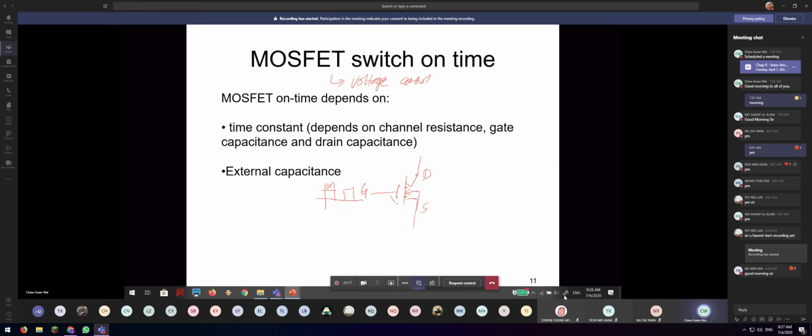Of course, you need to have a sufficient VGS to make it on. Normally the value is about 4 volts, for example, 5 volts. It's quite high sometimes, the pulse required. So you need to make sure you have a proper drive to make it turn on and off as fast as possible. Okay, MOSFET is voltage driven, not current driven, because the input resistance of the MOSFET is very high, so there's no input current. So basically, ideally, IG equals 0. Okay, remember this.